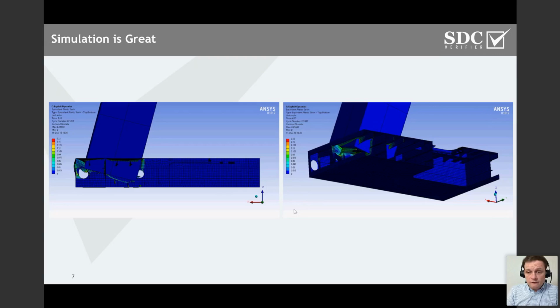You can do this kind of fancy simulation. I'm not speaking about all the possibilities of finite element analysis, but finite element analysis provides you with a fairly limited set of outputs. So you have forces, stresses, displacements, maybe some dynamic analysis will give you the strains, the plastic strains, or, like in this case, the amount of energy, but it does not necessarily answer your question of whether your analysis is completely okay.